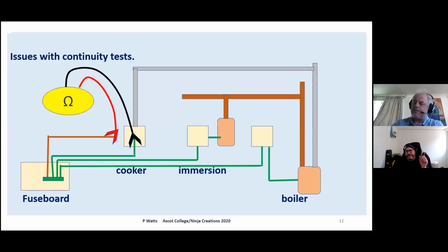Moving on from this, it's a bit about IR testing. When I deliver training, I always like the plug-in click roses you get. Any connection like that, or a simple plug-in connection, is great because you can fabricate the system and then simply unplug to test. You haven't got to dismantle, you haven't got to break it down. And if you connect your system into a plug system, even in domestics, you can get the equivalent ones. You can simply have them all unplugged and then do your testing. And there's no reason not to test.